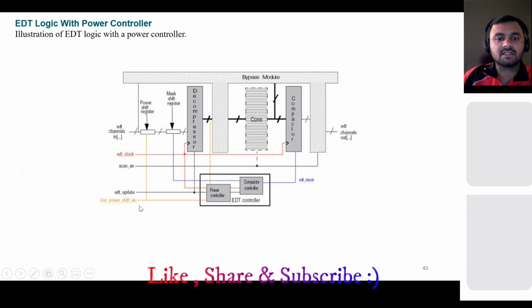There is some other logic we use here, and it will be implemented at the output of the decompressor, the input to your core internal chains. Based on that signal, your toggling will be less, and hence your power will be reduced.